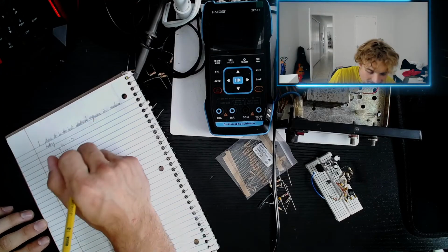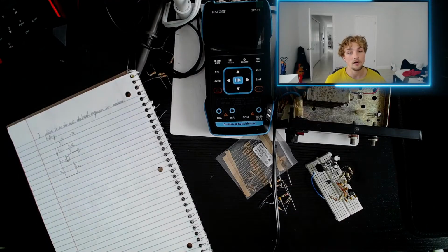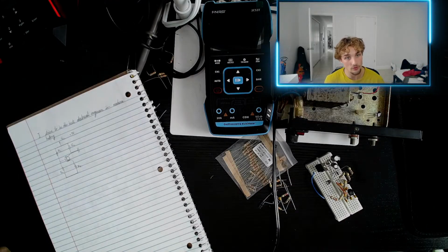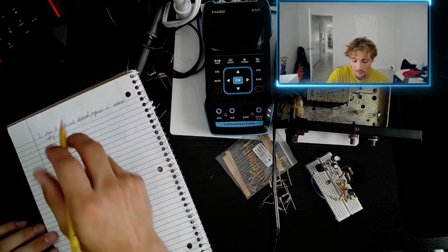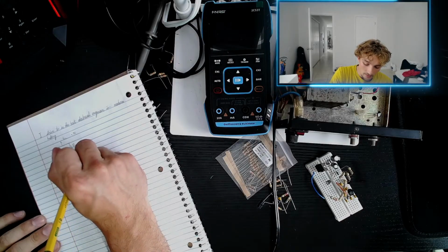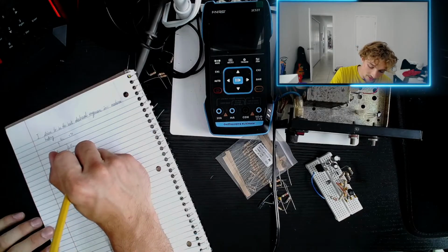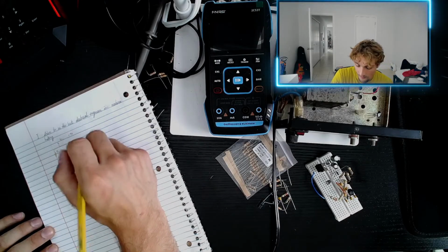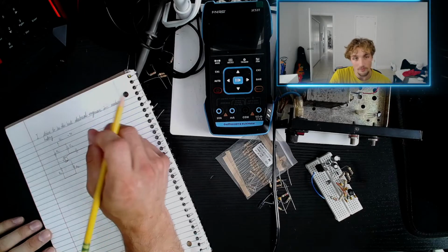We're going to have a decoupling capacitor here so that none of our DC transfers through to our LC tank. We only want our AC getting through, and so this decoupling capacitor attenuates our DC, I suppose we could say, and passes the higher frequencies, right? DC essentially would be a frequency of 0.